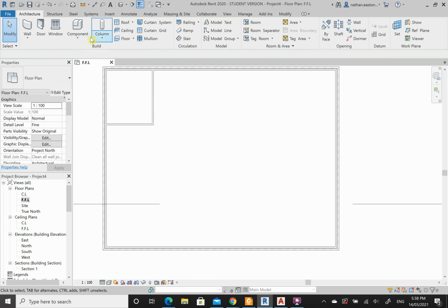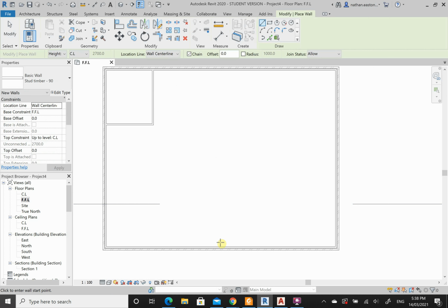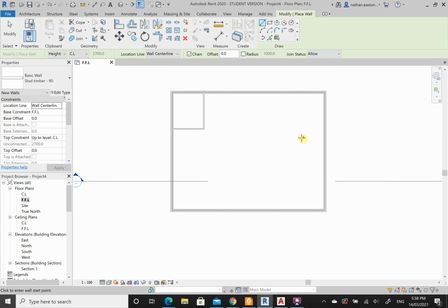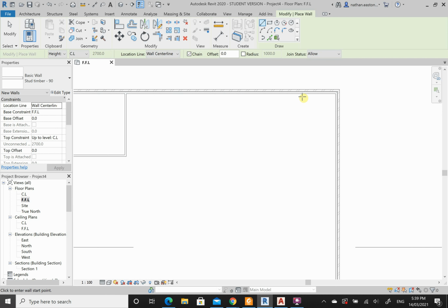Alright, let's come in with some more walls. Let's put another one here somewhere, from this corner here. Tab is really useful. The tab key shifts the reference line or what you're trying to select, and you'll use that a fair bit as we progress. So let's come through and go 3500.